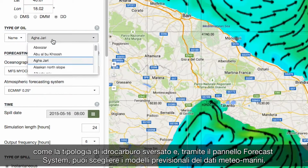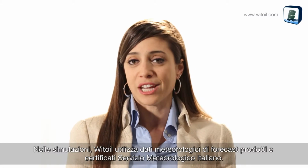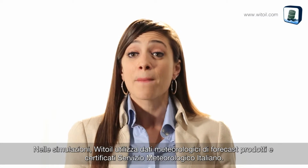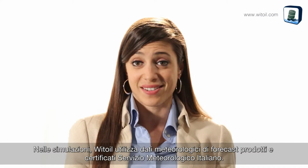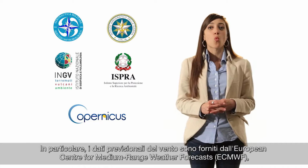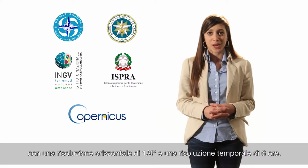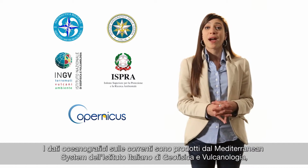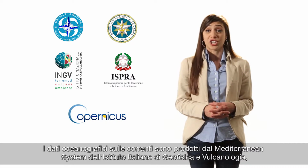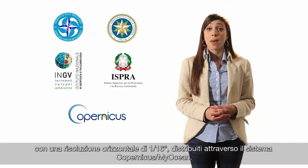And via the Forecasting System panel, you can choose the Weather Oceanographic Forecasting System. In simulations, Witoil uses meteorological forecasts produced and certified by the Italian Meteorological Service. In particular, the atmospheric wind is provided by the European Center for Medium-Range Weather Forecasts at 1/4 degree horizontal and 6 hours temporal resolution. The ocean current is provided by the Mediterranean system of the Italian Institute of Geophysics and Volcanology with 1/16 degree horizontal resolution and delivered through Copernicus, MyOcean.